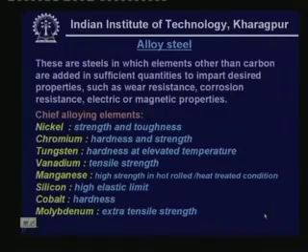So tungsten steels are one of the very hard steels, and in certain cases, if you are using small bearings of journal type, you can sometimes use tungsten bearings, which, because of their hardness, won't wear out that rapidly. Vanadium simply increases the tensile strength. Manganese gives high strength in hot rolled and heat treated conditions. Silicon imparts high elastic limit.